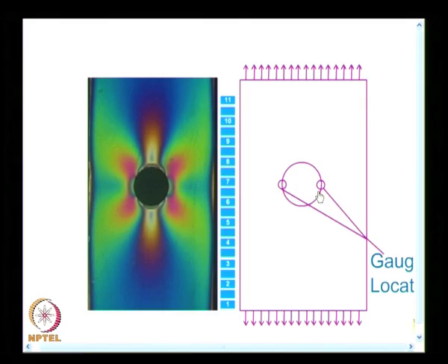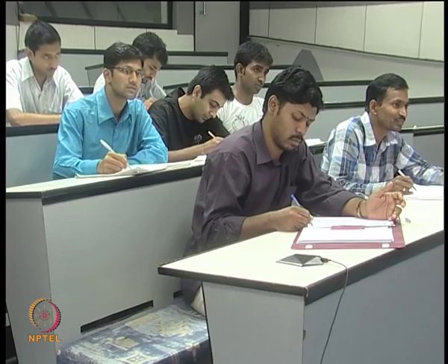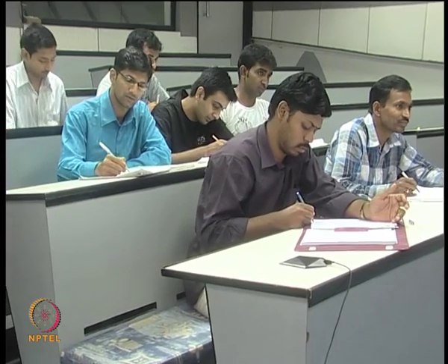All these are a difficult proposition. If the hole is very small, what will you do? So, you appreciate a point by point technique, how difficult it is to apply in stress concentration zones. I had also mentioned that the rudder of Concorde was failing, they used a strain gauge. They found that the strain gauge was measuring strains lower than what is actual, and a photoelastic coating test revealed that maximum strain was at a slight distance away, and they had corrected it.